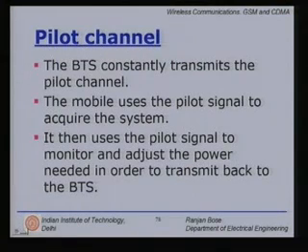So, please remember, this is the near-far problem in CDMA systems, where there is a threat of a mobile close to the base station drowning the signals coming from a mobile far away from the base station. Hence, power control is essential for the proper working of CDMA systems.